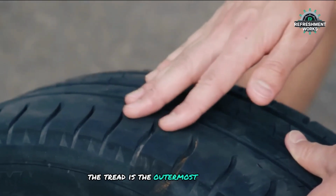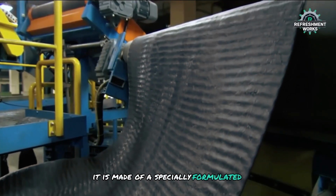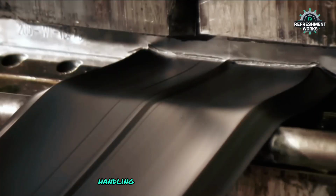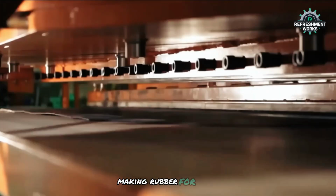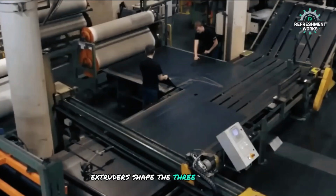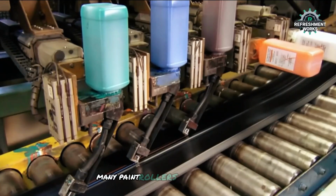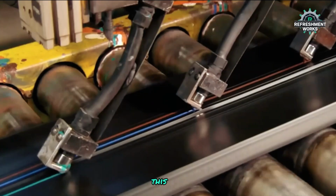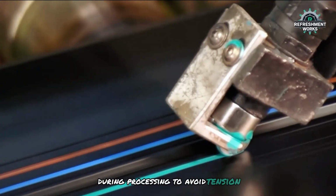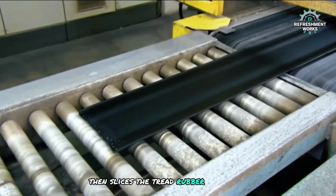The tread is the outermost part of the tire that comes into contact with the road. It is made of a specially formulated rubber compound with unique patterns and designs for optimal traction, handling, and wear characteristics. Making rubber for tread requires 3 different rubber formulations. Extruders shape the 3 streams of rubber, and then they enter a die that forms them into one. Many paint rollers apply different colored stripes. This way, the factory can identify the different ingredients during processing to avoid tension. The system creates slack in the feed blade, then slices the tread rubber to length.